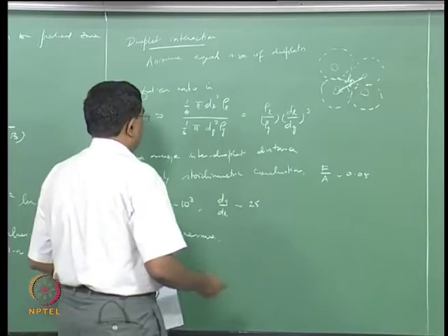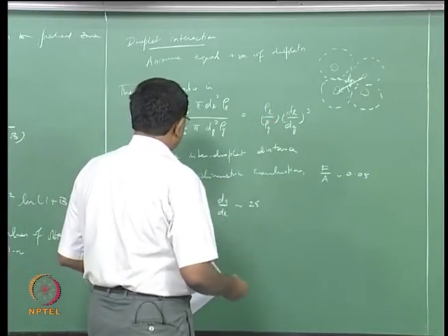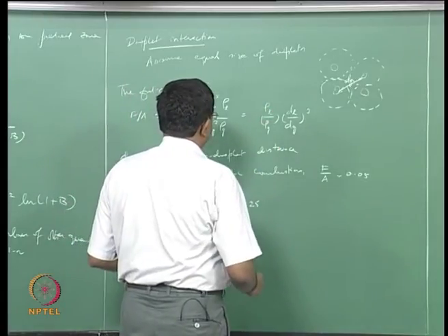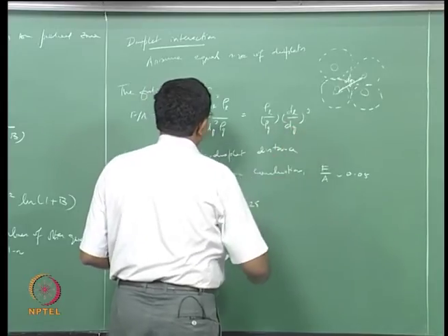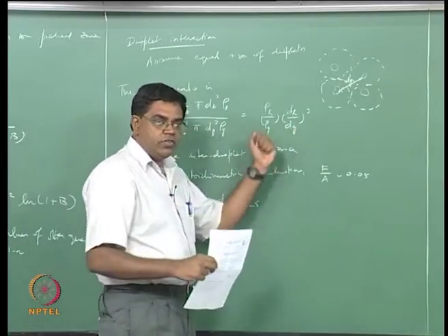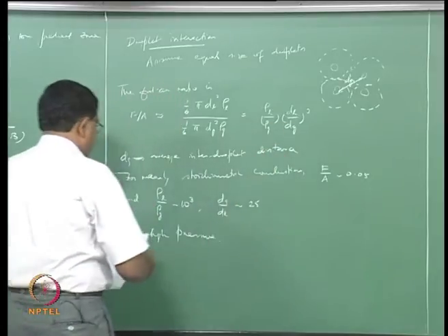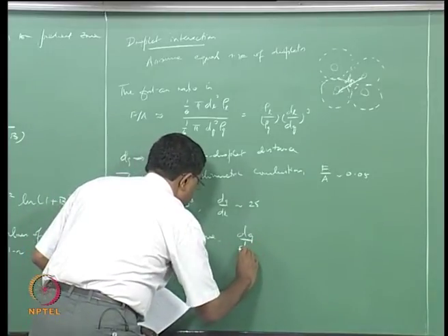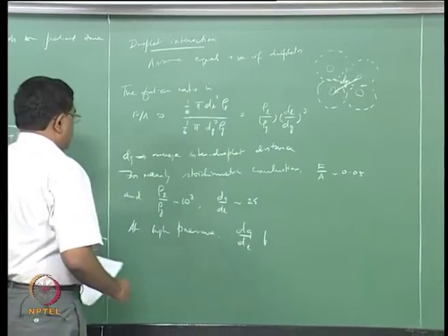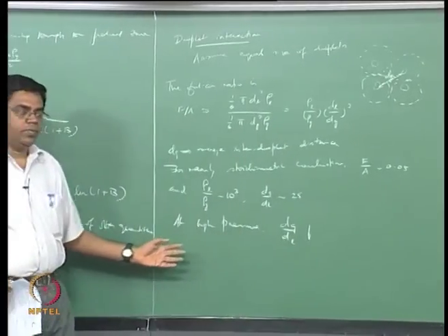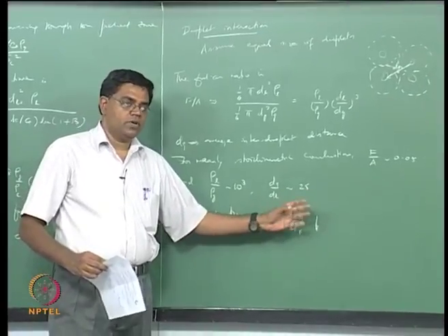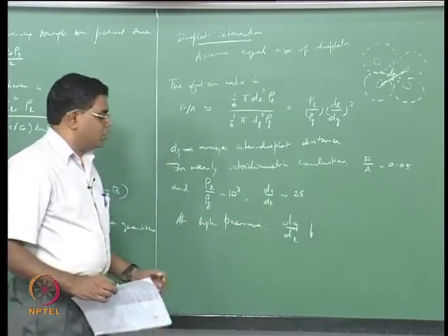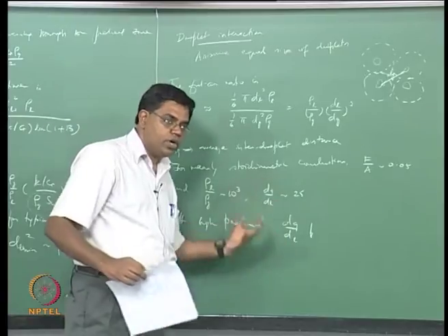So if rho L over rho g, if rho g increases, rho L over rho g decreases. If rho L over rho g decreases, then dl over dg will increase, or dg will decrease effectively. So dg over dl then, dl decreases. For example, in automobile engines, if you look at the typical pressures, you will find that those dg by dl would be lower, like about 15 or something, still greater than 10, but you are now hitting a limit where you have to consider the interactions.